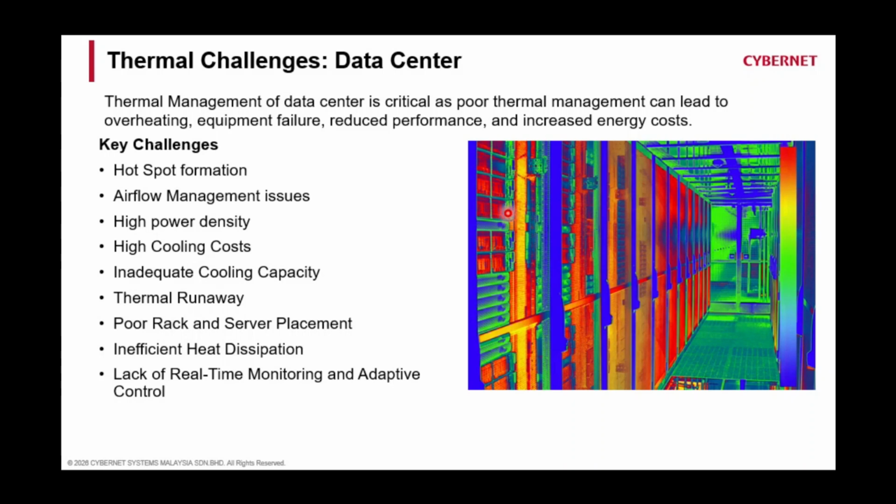Thermal management is very important for a data center because, without proper thermal management like airflow cooling through all these servers, heat accumulates, causing overheating and ultimately maybe equipment failure, or even the risk of fire or smoke. You will not want that in the data center.